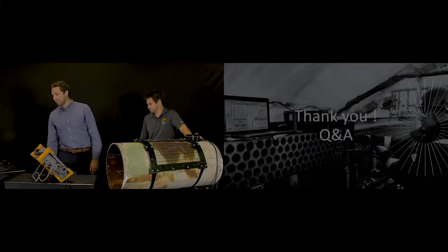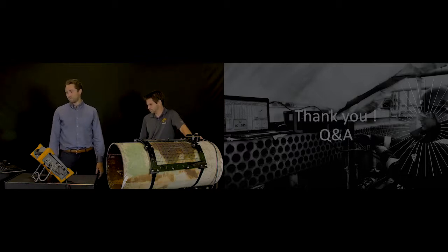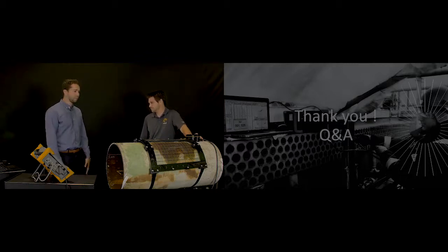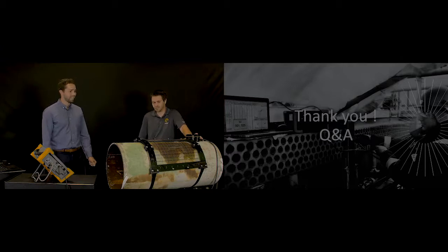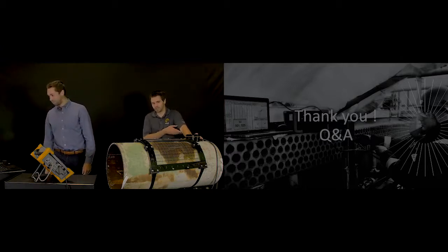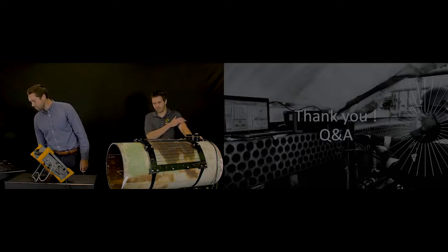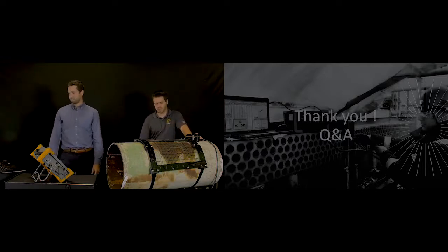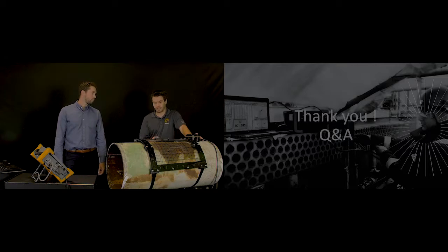If the scale has been removed, does it still work? Yes, of course it's going to work if the scale has been removed to do an inspection with another technique. The lift-off system is still going to work. If there is a lot of scale, it can affect the quality of PEC signals, but with this probe we really improved the sensor design to minimize the scab effect, any detrimental effect you could get on the signal because of thick corrosion material.